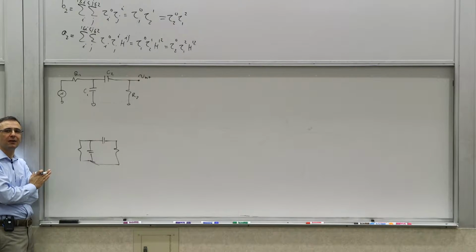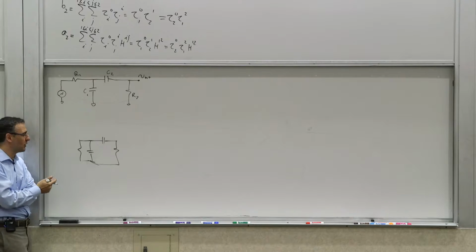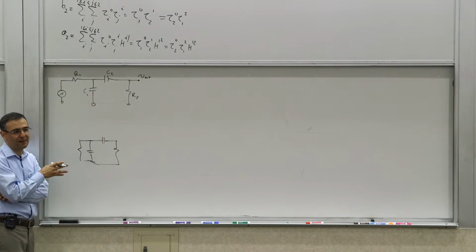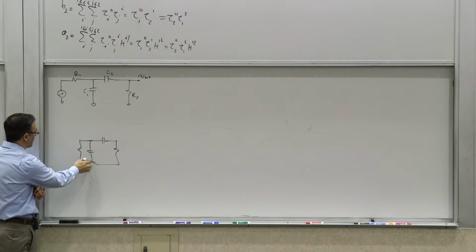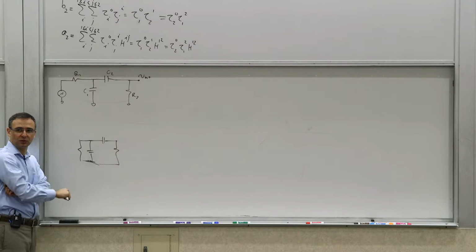It's an okay question. What are the natural frequencies of this network? You can do it. Of course, you have to think about whether your independent sources are shorted or opened. You have to have nulled the independent sources properly. In this case I have, because I short-circuited this one, so it reduced to this.